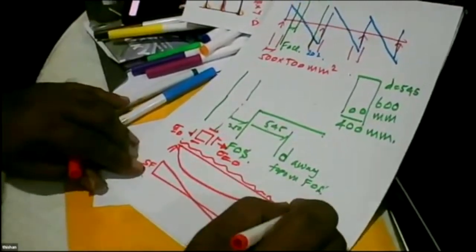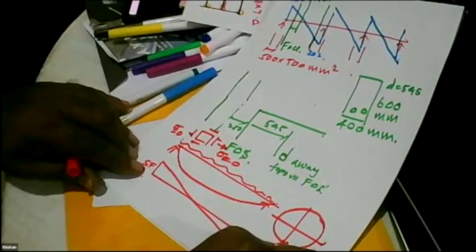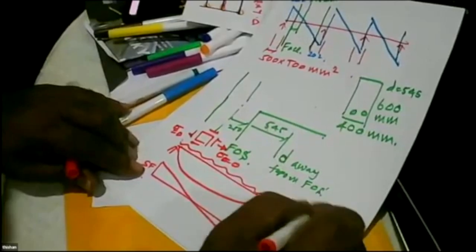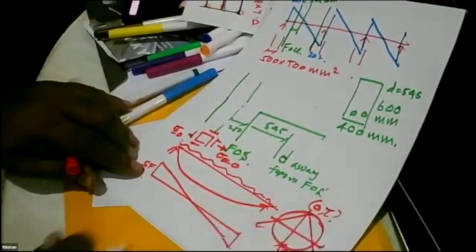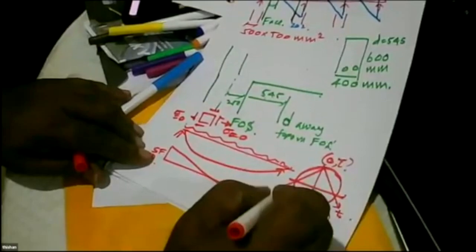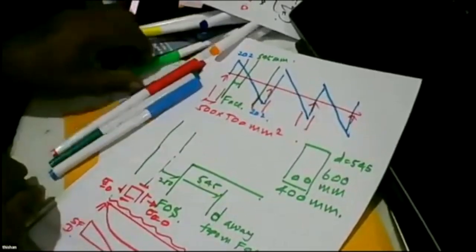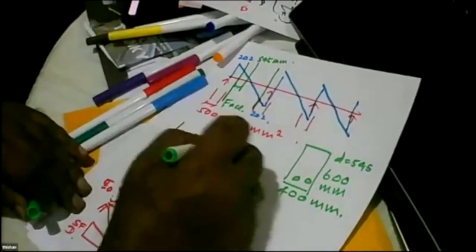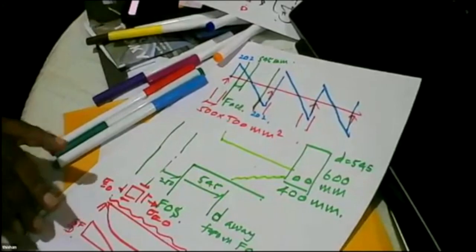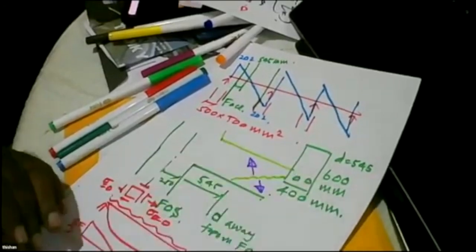So you can draw a Mohr circle: 0, tau, minus tau, 0, tau. And you find the principal stresses are like this: tension, compression. So what is the failure type? It's shear. What is the failure? A crack like this, where the tension is pulling it that way.